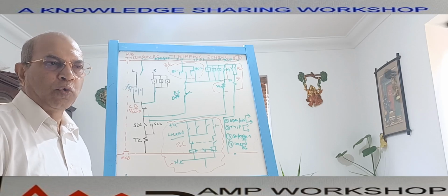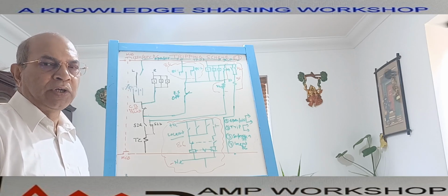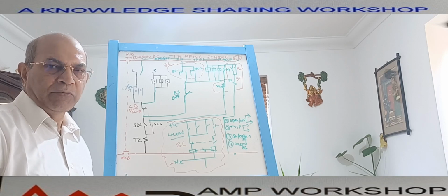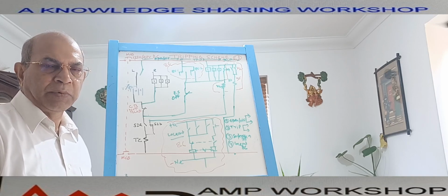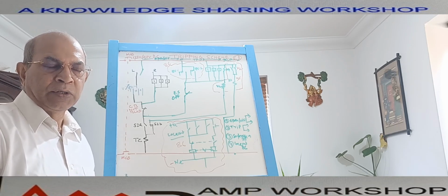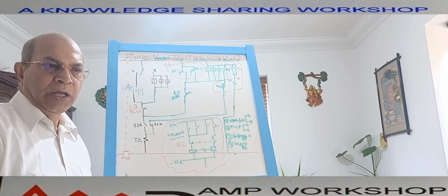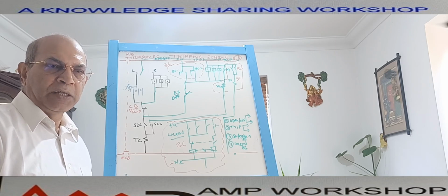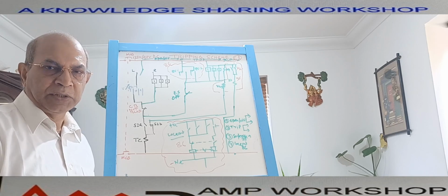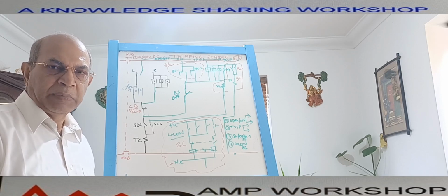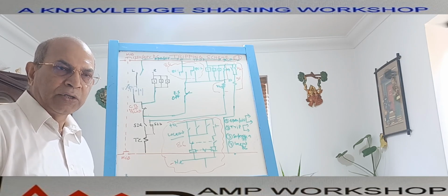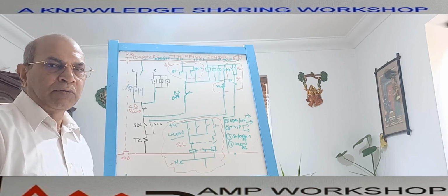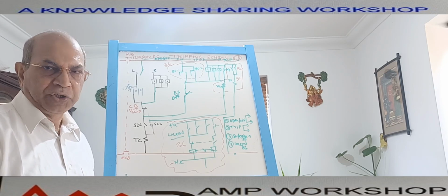The opening of a circuit breaker means we open the circuit breaker from the closed position knowingly. That means by manual intervention, when I open the closed circuit breaker for operational purposes, testing purposes, or maintenance purposes, at that time we are opening the breaker, but there is a healthy condition in the circuit which the circuit breaker is feeding power. To do the maintenance work or for any operational reason, we open the breaker. That part we call the opening operation.